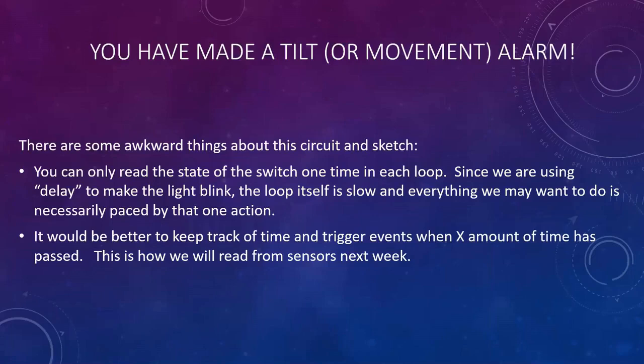And then you can start the void loop over again and read the state of the switch. It doesn't really make a whole lot of sense to be reading a switch only once every 300 milliseconds or so as the pin 13 is making a beeping sound happen.